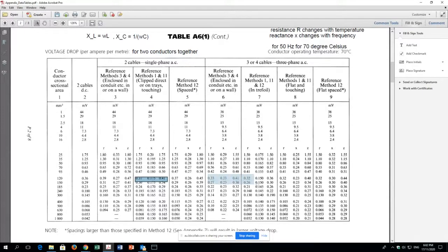And for the three-phase case, it is much more different. In the three-phase case, the currents on the conductors have a big phase difference. Remember that in the DC case and the single-phase AC case, the current in and the current out in the two conductors are opposite to each other. But in the three-phase case, the phase angle difference between the currents on the conductors is 120 degrees rather than 180 degrees. You will see this in the three-phase systems. Here we do not talk so much about it.